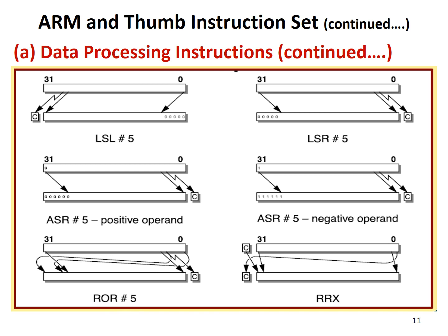Similarly here, for the arithmetic shift right, instead of 0 there is a 1 in the MSB position. So after shifting, the empty places are filled with 1. Then rotate right. For rotate right, bits are shifted towards the right and the empty places are again filled with the shifted bits. So that is rotate right.